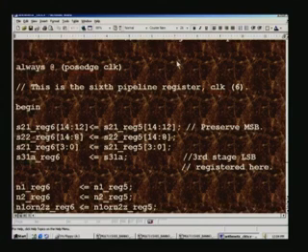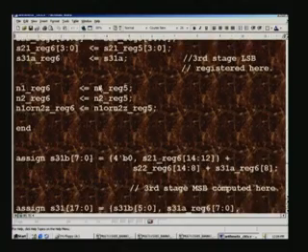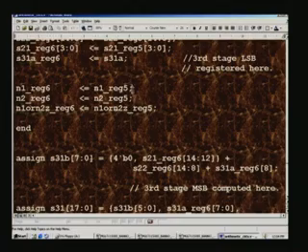And when the clock strikes we should also preserve the MSB because we have not yet processed it, and that is what we are doing here from the previous stage, and propagating it through some other register here. This is the third stage LSB, and they are also registered here. So, the LSB we have just now processed there, and we should once again take care of the 2 sign bits as well as the 0 result registered here.